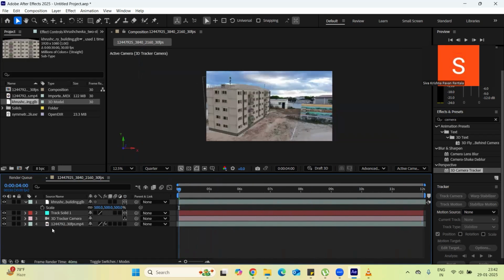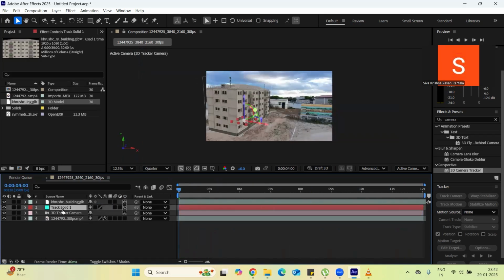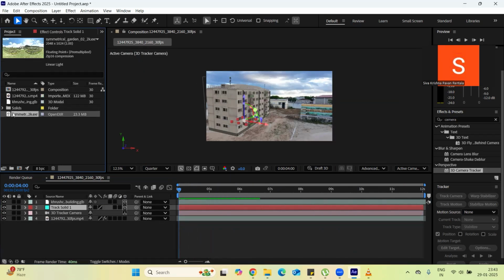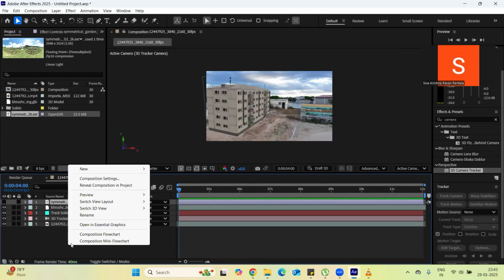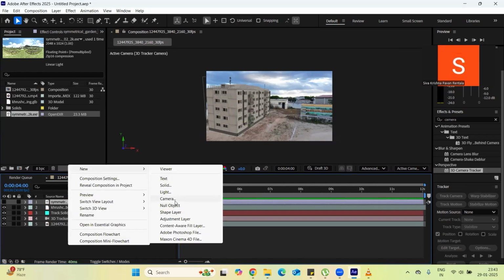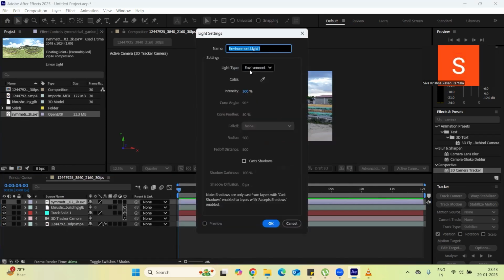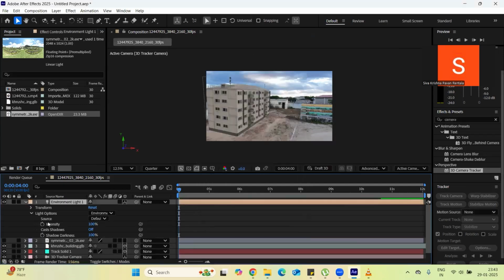So to do this one more, if you see we have a ground plane too, to get some lights and shadows. Use your HDRI image, what we have, and you can get it from polyhaven.com. Bring your HDRI into the scene. You can turn it off, go to the new lights. Get this new option called environment light. Hit OK. Under the source, choose your HDR.